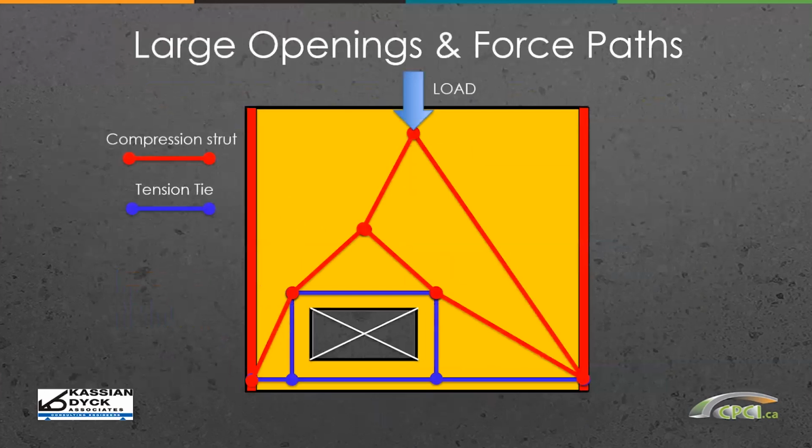And again, depending how the engineer is developing his model to examine the strength of this diaphragm, we may decide to use some type of truss approach where we're looking at transferring the forces through and then putting reinforcement in the regions where we get tension. And again, tension reinforcement around openings, if you're doing this type of approach where you've got fanned compression struts and tension regions, you really need to look at the strength of those zones and these nodal zones where the elements are coming together of tension and compression, and potentially extend your reinforcement well past the opening.